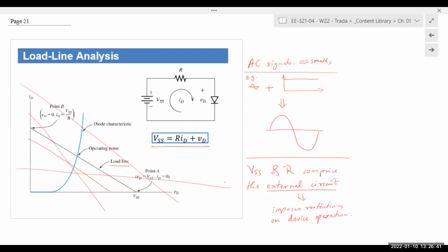So depending on the external circuit, depending on my application, I would design the external circuit, and using the exact same component, I can change the operation. Yes, at least for this circuit. For a different circuit it could be something else. But load lines, for the most part, will always be linear, because one end would have one quantity be 0, like one voltage would be 0, and the other time the current would be 0.